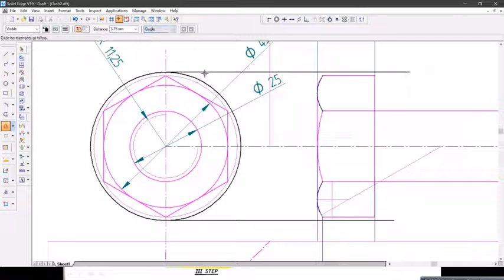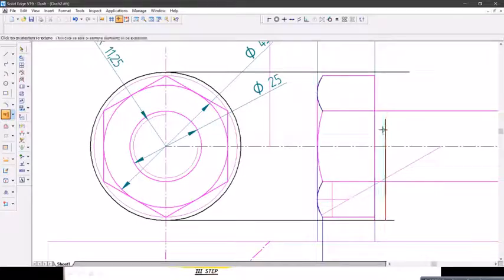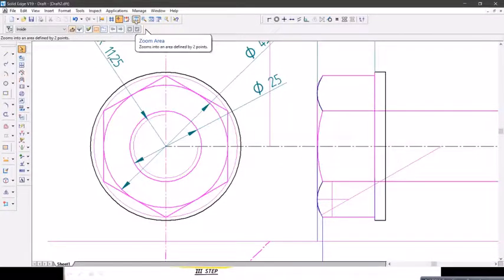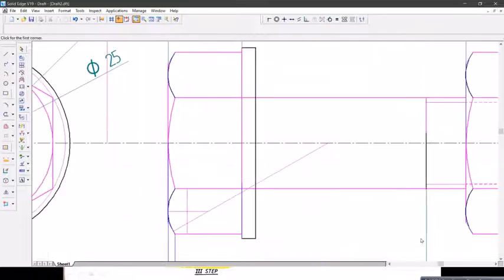Now what is the thickness? 0.15 into 25, that is 3.75. Select single, place it on right side. Now extend. Now trim unwanted portion. Now this is what washer. So you need to leave 1 mm inside as a free space for easy rotation purpose.